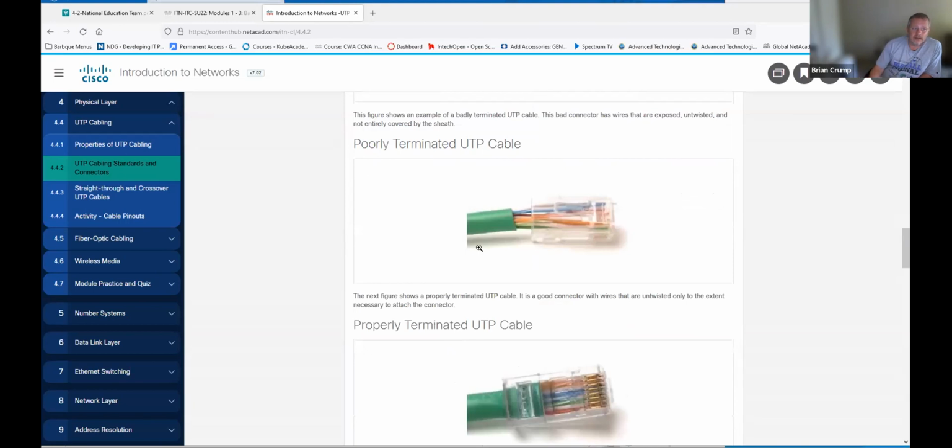This right here, if Jeff Swearingen was on here, he would just take the end of it. And Jeff works with us at Stanley. John knows him. If a student were to bring him a cable that looked like this, yes, the wires have been inserted correctly, but they did not have the copper clad shielding far enough inside of the connector and crimped correctly like this one is. He would take a cutter and literally snip it, give it back to the student, and say redo it.